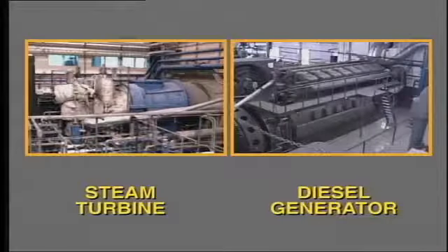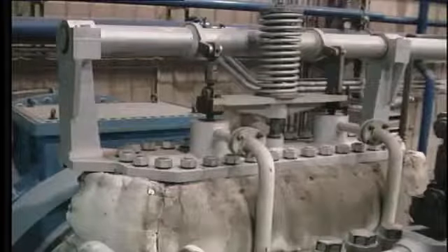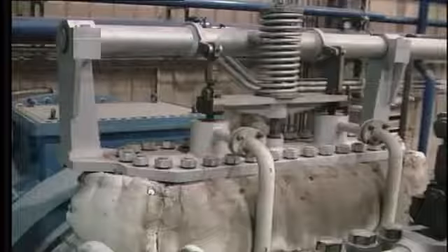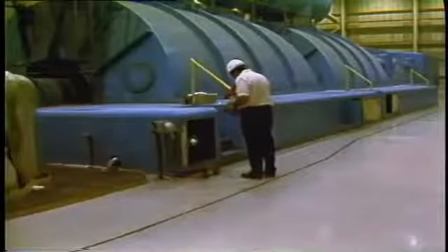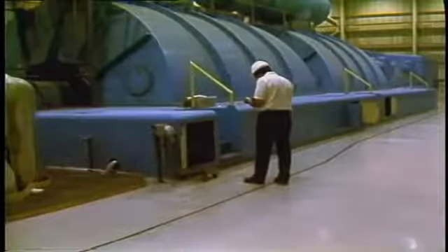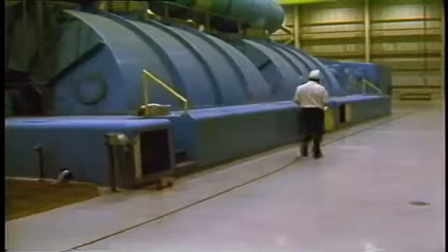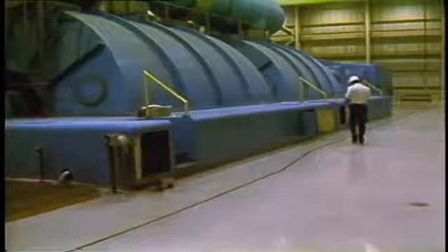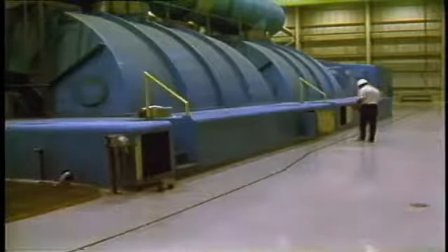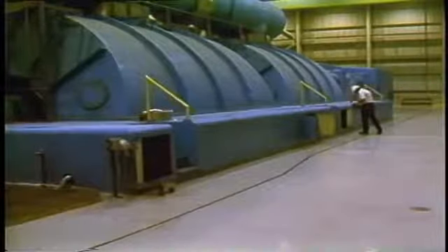Another advantage is that the steam turbine is far less complicated and contains very few moving parts. The moving parts are the rotor, which drives the generator, and the steam control valves and control gear. The amount of vibration produced by a steam turbine generator and transmitted to the surrounding area is relatively low, provided, of course, that the machine is in good condition and is correctly installed and aligned. This makes for a quieter operating plant, particularly when compared with the diesel engine or even the gas turbine.